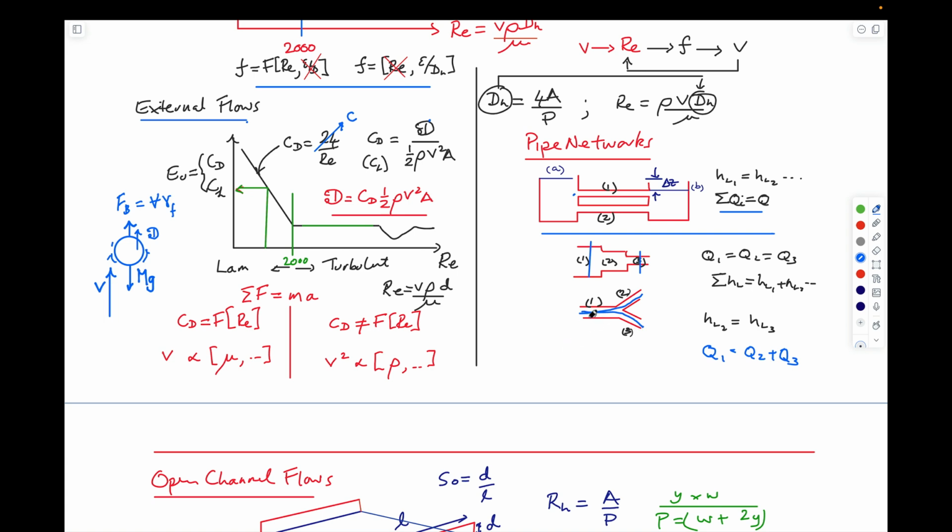Also, you have to bear in mind that in writing the energy equation, you need to write it in the direction of flow from upstream to downstream. So if you get one of these questions, you have to write the expression in the correct mode.